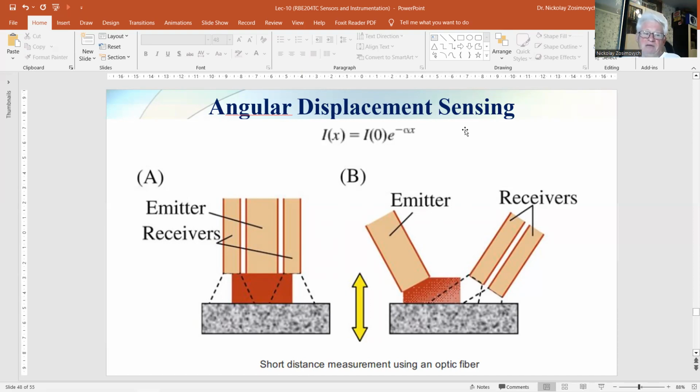The mechanical types are based on a free-moving pendulum that always points downward, also when the housing makes an angle with the Earth's north. At the pivot of the pendulum, some means of displacement sensing is connected, which gives an output signal that is related to the angle.